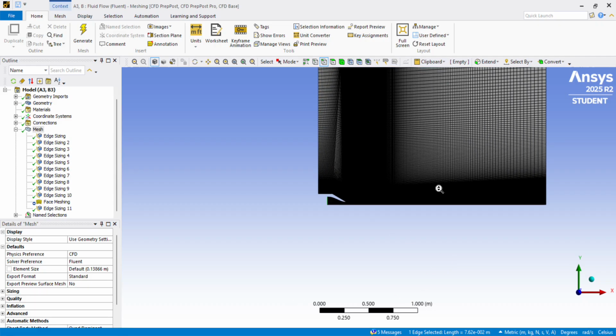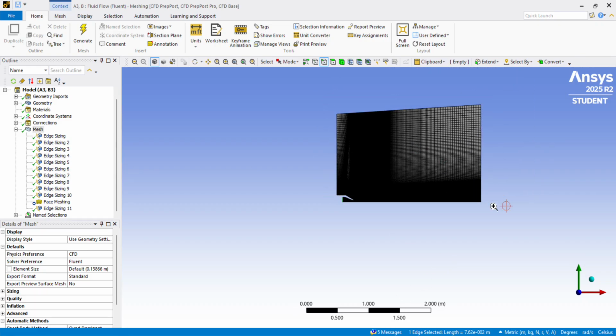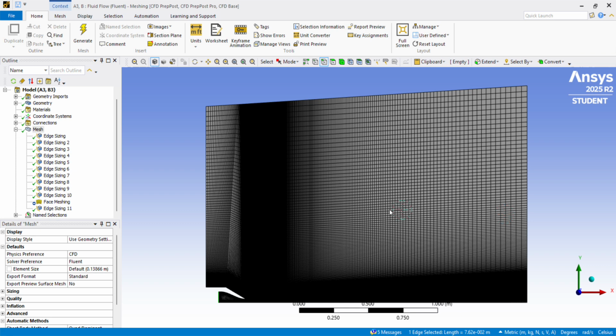And yeah, we were able to do it. So it's good if we just follow the steps, but we will not be able to get to this mesh at one time. It needs some hit and trial, because you don't know at what number of divisions and at what point you will be able to get that mesh. So until you do it 3 times, 4 times, 5 times, or maybe 10 times, you will not be able to get it.